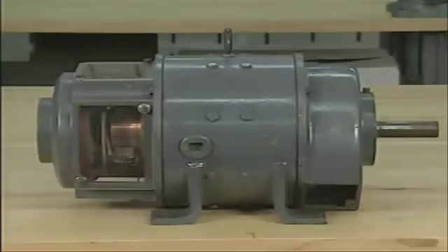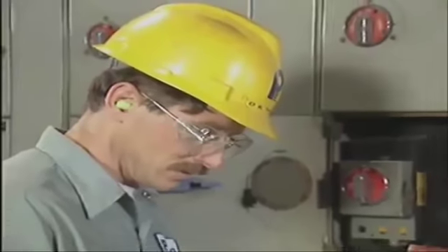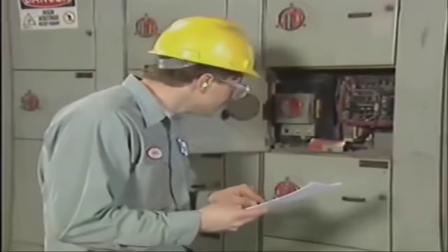The external appearance of all DC motors is very similar, but there are several ways to distinguish one type of motor from another. For example, this is a nameplate from a typical DC motor. The entry in the block labeled wound identifies the type of motor it is. In this example, the block contains the letters CPD, which means that the motor is a compound motor. You can also determine what type of motor it is by referring to a schematic diagram in the manufacturer's manual.